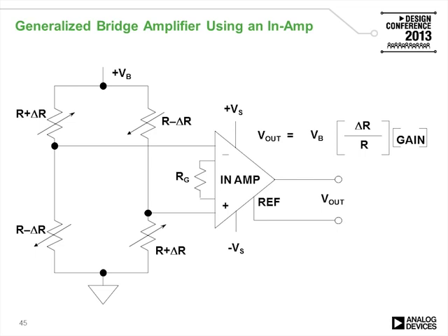Instrumentation amplifiers are typically used for amplifying bridges as well as biopotentials. As seen in this example, a bridge creates a small differential signal between its 2 terminals. Because of the high source impedance of a bridge, a high input impedance is required as well as high gain. This is why an instrumentation amplifier is the perfect solution for this type of problem.